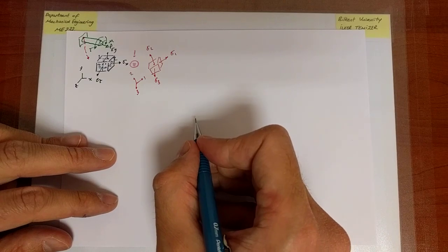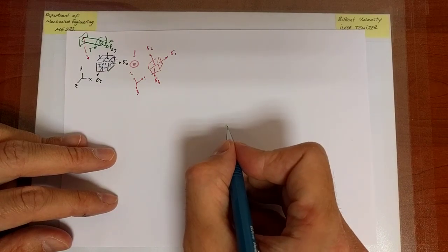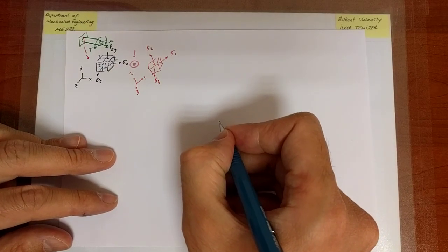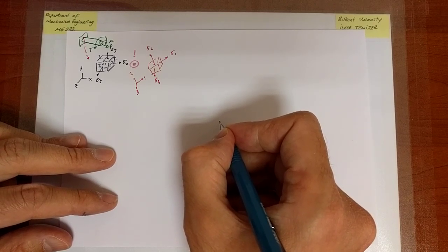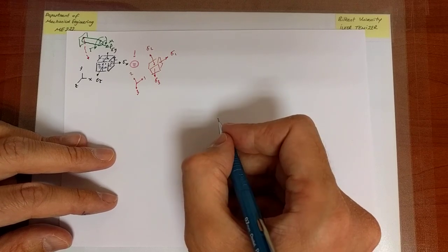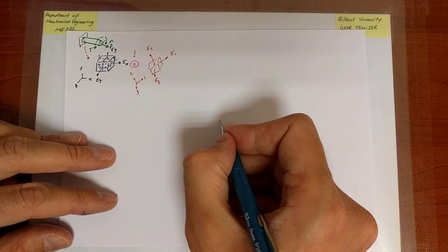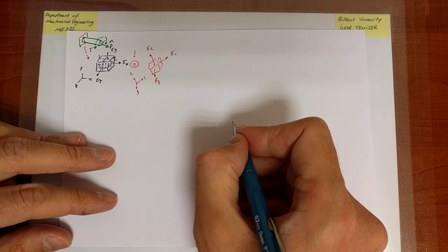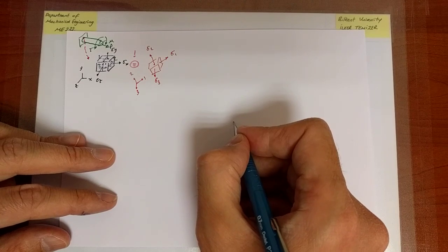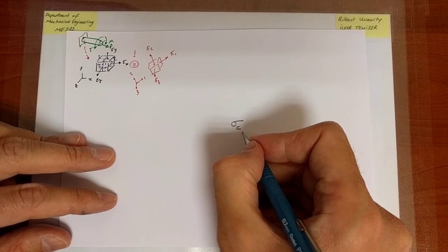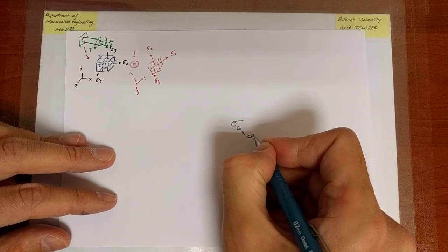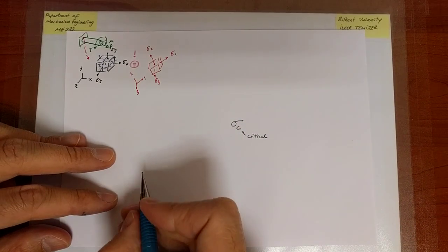So first of all, if I have a uniaxial loading scenario, I know that failure occurs at a certain critical stress. Failure for me at this stage might mean the yield strength of the material or the ultimate strength if I'm working with a brittle material. In either case, we will have a certain critical value of the stress that we do not wish to exceed. So C for critical.